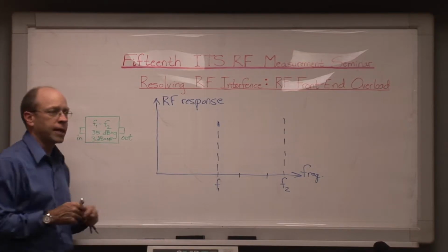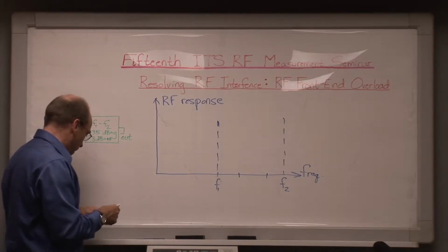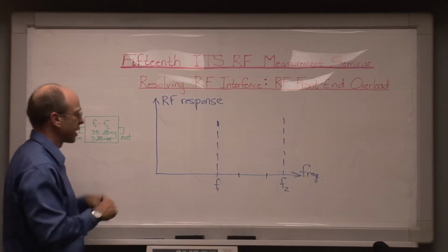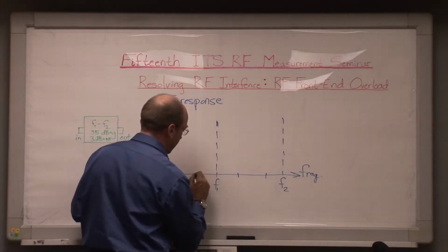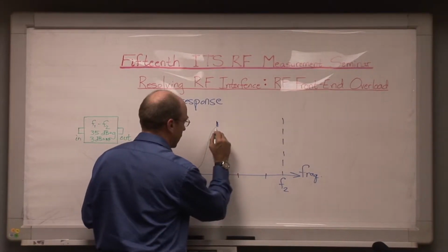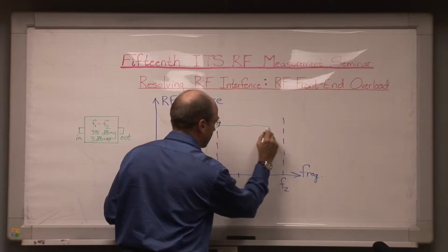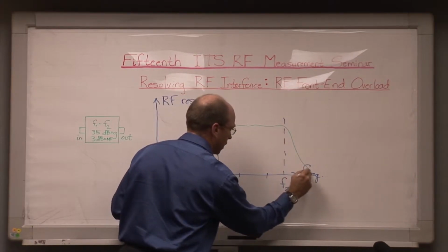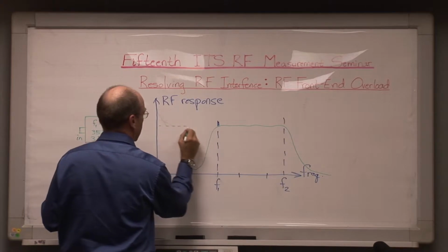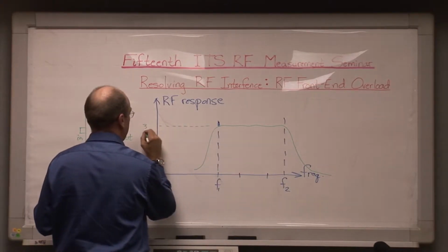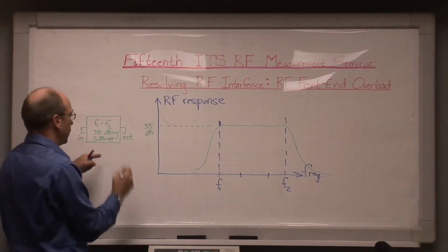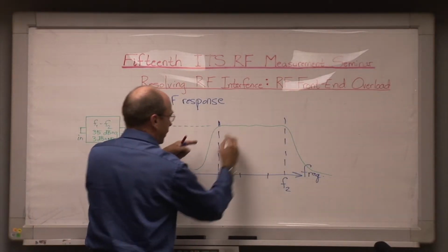You go ahead and you insert that into the system. Now, the mental model that a person has typically developed at this point for this low noise amplifier is as follows. The person typically envisions the low noise amplifier as having a frequency response that looks something like this, where they're imagining that this represents 35 dB of RF gain with some fairly low noise figure across this range.